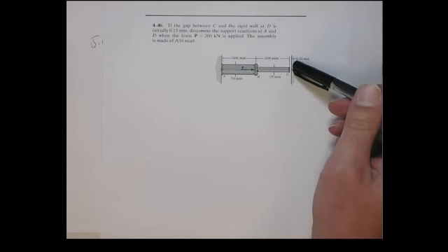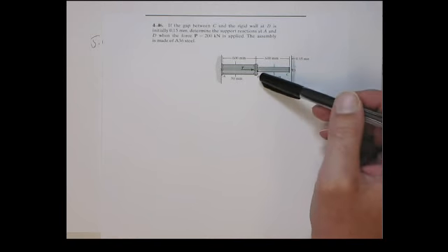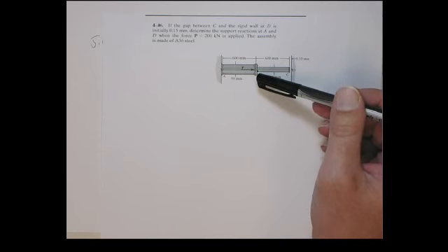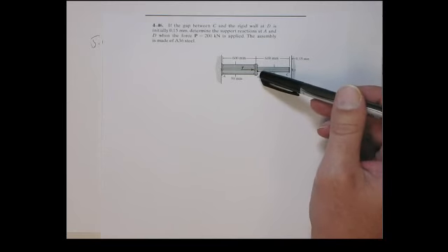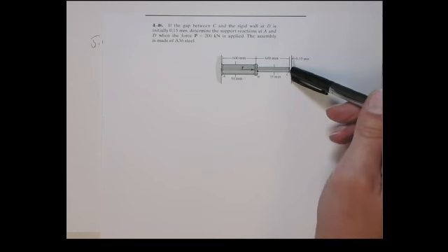Okay, so what's going to happen here is if the force at P is sufficient to elongate this such that it comes into contact at D, then it'll become a statically indeterminate problem. Probably you can infer from this that they set up the problem such that P is large enough that this section stretches more than 15 millimeters. Then obviously we have a statically indeterminate problem. We need to figure out the reaction forces at D and A.